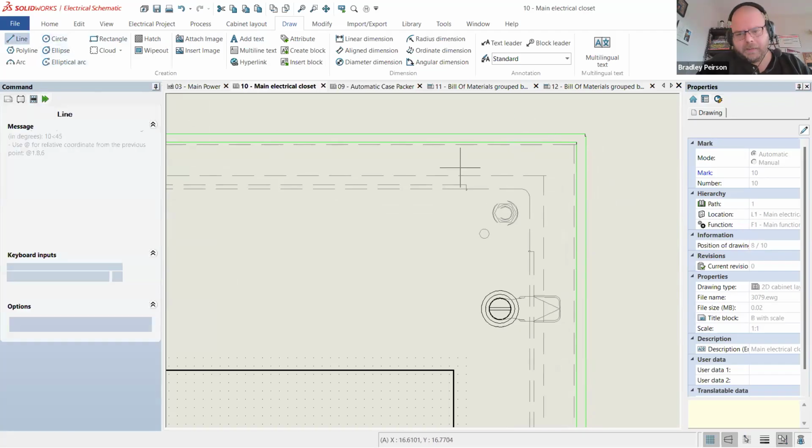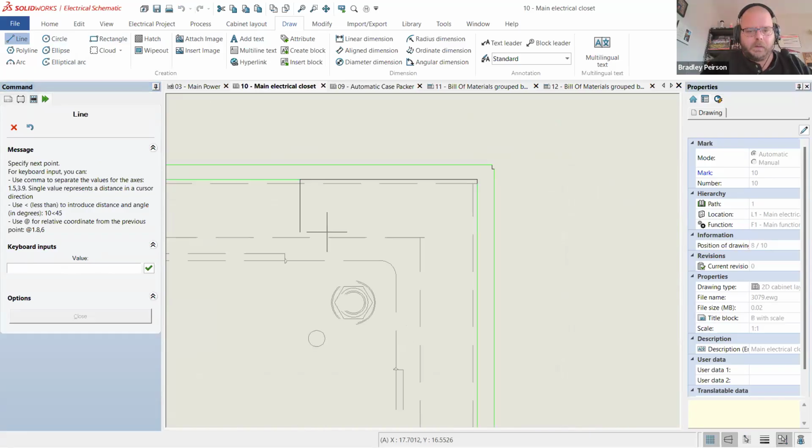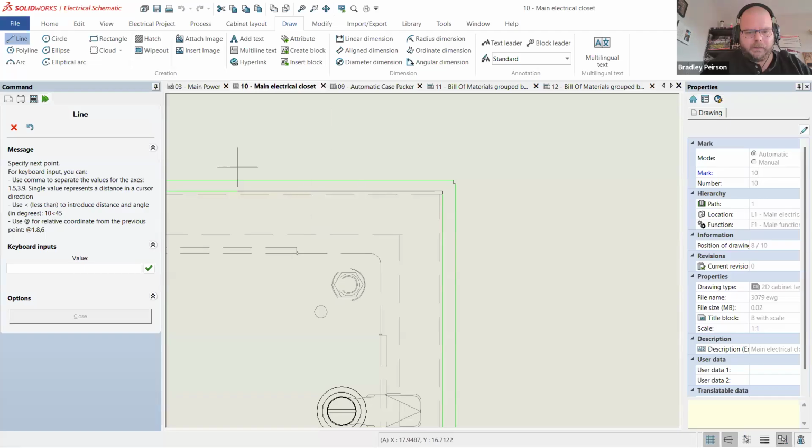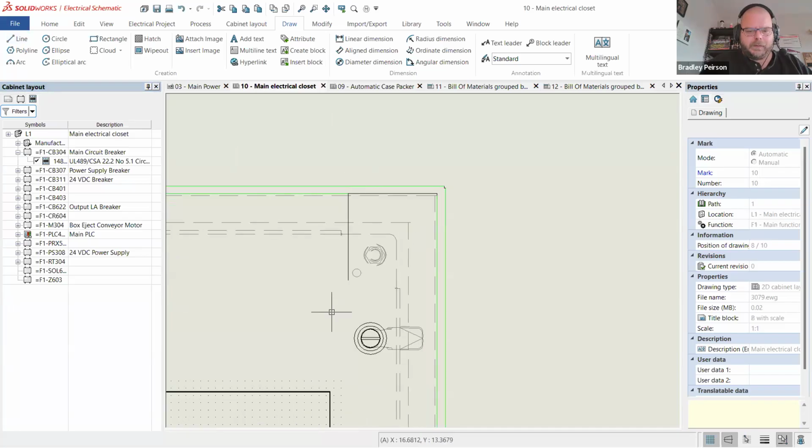Trying to make it as easy for the cabinet builder as possible. So I want that to be at -3 comma 0. So that's 3 inches long now, right? It's this line that's stuck is 3 inches long, and I can come down now at 0 comma -3. Okay. And now it's 3 inches in, 3 inches down.